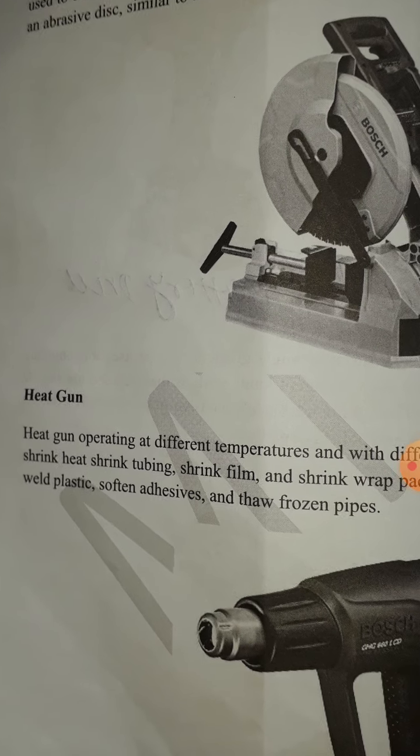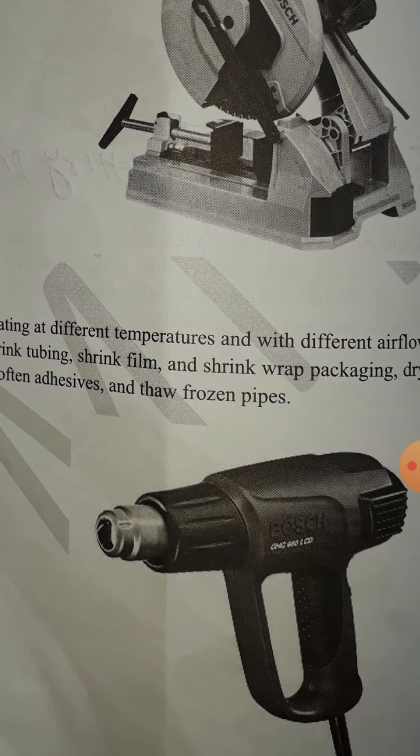And the heat gun. This heat gun we can use for heating the sleeve. I already told you about lugs and termination time. There are lugs for cable, cable core lugs, armored cable and non-armored cable. Heavy lugs are there. Big lugs come without insulation. So that time you can crimp the lugs with crimping tools, and then after put the sleeve as per your color code.